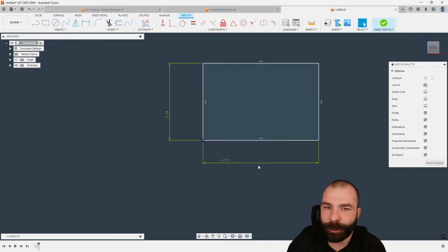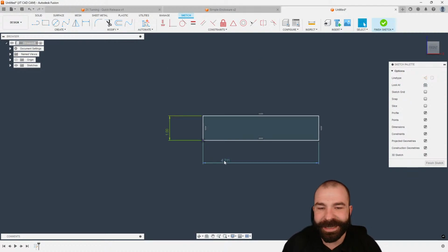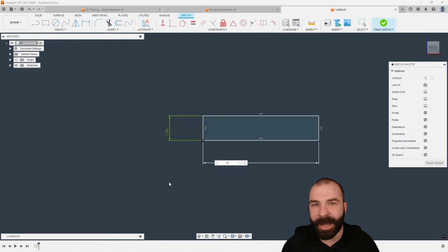times my length, right? So if I went in, and I'm going to make this a solid number for those of you out there so you don't have to take your shoes off to count the 20. But let's just say, for example, now I want this dimension here. I'm going to click the 1 inch that I just drew. Now what you're seeing is D1 has self-populated because that was dimension 1. That was the first parameter I put on this part, right?